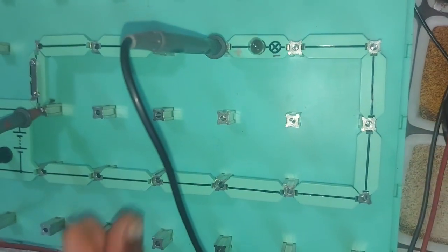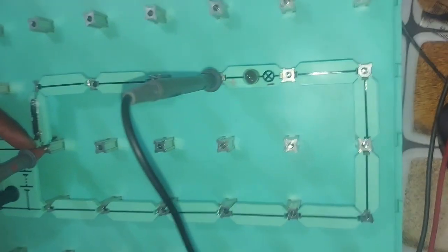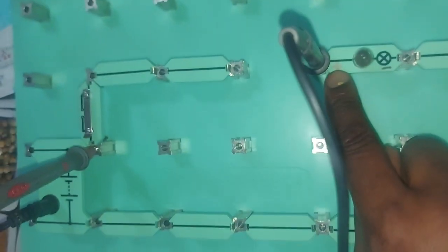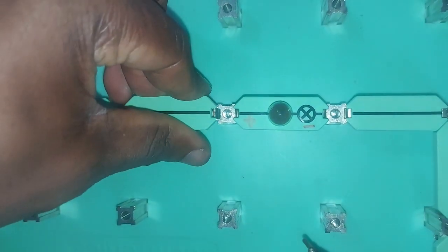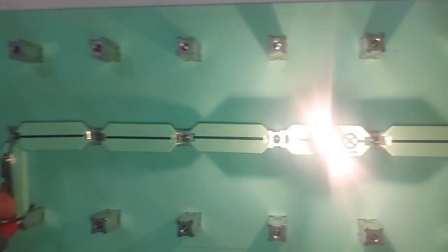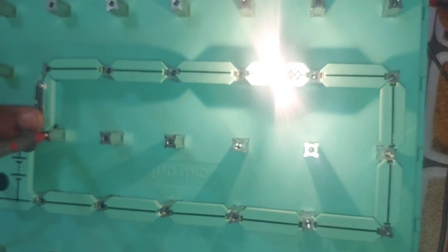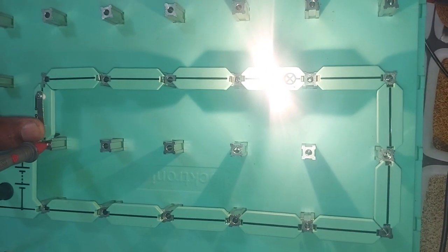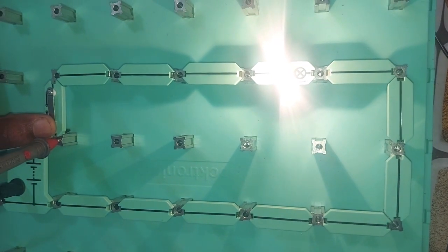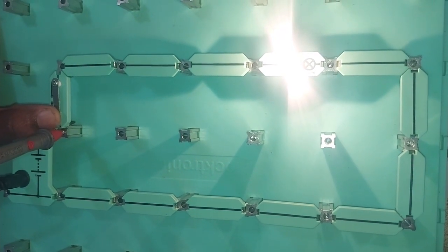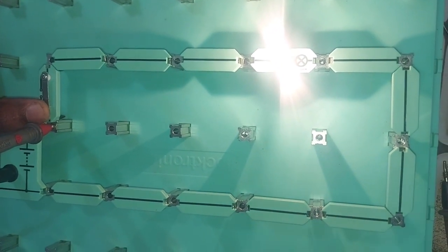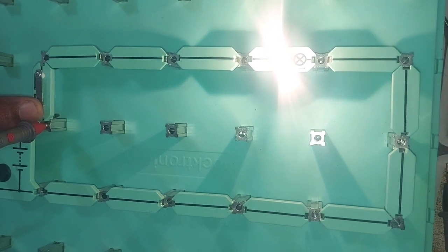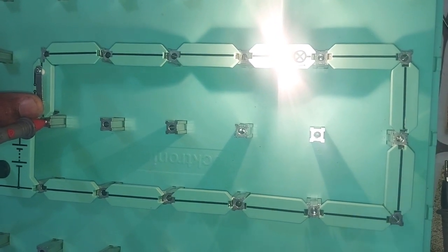So because we are on the positive here, the short is found on the positive side. So if we fix our positive side and close, then the load will work. Is that not a perfect way of diagnosing problems? I feel so good when I'm talking about these things, because I know what they can do to a technician when you're working on a problem.